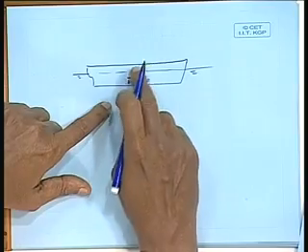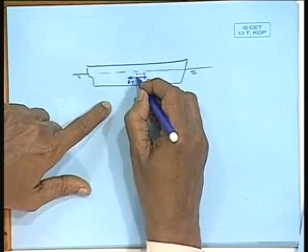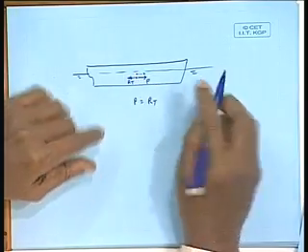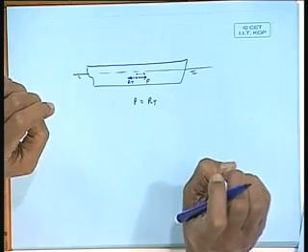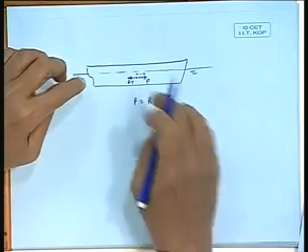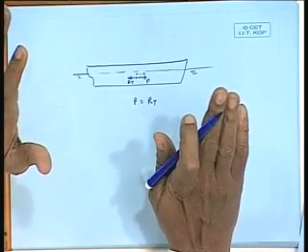One of the assumptions we made for any calculation on resistance, that between model and ship, the trim should be similar, geometrical similarity has to be maintained. Now, by putting the tow rope point somewhere above where the resistance worked, I will be introducing a small trim. Now, since I do not know where the resistance is, I cannot help it, it will come, small error will be there.